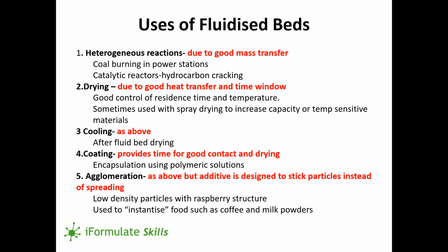Also sometimes used at the back of spray drying processes to increase the capacity of a system, whereby you only partially dry your particles in the spray dryer to form a particle which can be moved about in a fluid bed, and then you can increase the amount of drying you do by putting it through a fluidized bed.